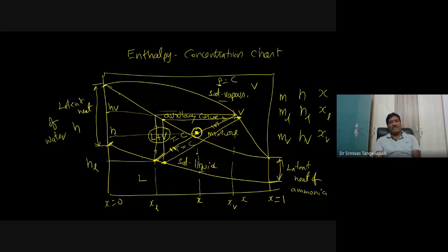I'm going to explain the formulation applying the lever rule, and the mass balance, energy balance, and exergy balance in case of the second law of thermodynamics, in subsequent thermodynamic processes. Because today I just outlined the reading of thermodynamic properties for the binary fluid system. With this information on the binary fluid system, I'm going to explain the solutions for various thermodynamic processes in the Kalina cycle system. And those are separation processes.